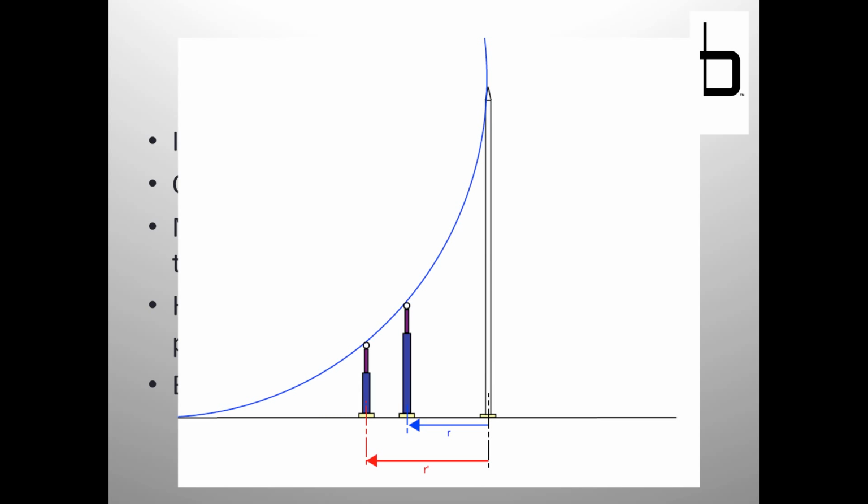Now, if you choose the highest point of your substation, let's say 30 feet is the tallest bus that you have, and you're able to protect your entire substation assuming everything was at 30 feet, it kind of goes back to the sphere. If you've protected against 30 feet, you've protected against shorter equipment as well. Equipment that's actually 20 feet tall will fall under that protection as well. So that's a way to simplify calculations, just going for your highest equipment.